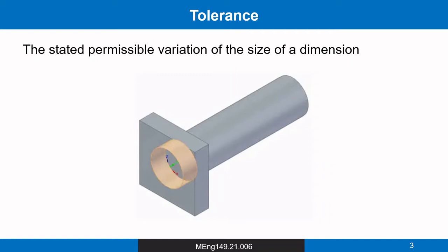Okay, in actual fabrication of either the gear hub or the shaft, minor adjustments have to be made, either you file down the shaft or enlarge the hole in your gear hub. Just an example.